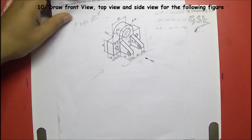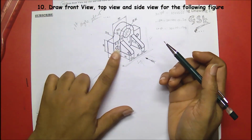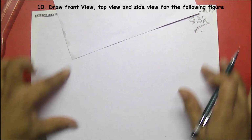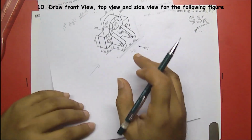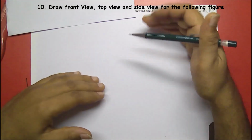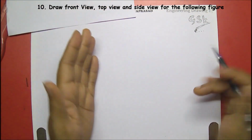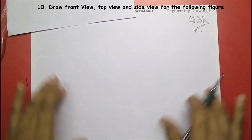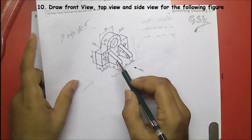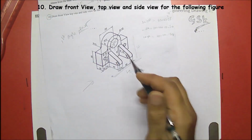Before going to the problem, just calculate the size or dimensions of the figure, so you can fit that in the particular drawing sheet. Without calculating that, don't go directly into the drawing. That won't fit the drawing sheet, or it will come onto another figure, or else it won't cover all the surface or all the area of your drawing sheet. So before going to drawing, just calculate the overall dimensions or a clear view of that one.